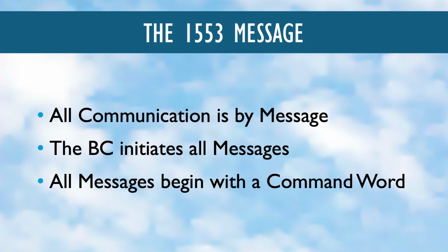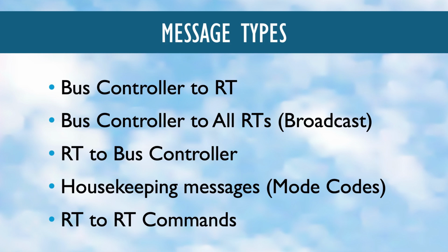We will see that there are a number of message types defined within 1553. All communication on the bus is performed using one of these message types, without exception. The first word of every message is a command word, and only the bus controller may transmit a command word. These strict rules guarantee that no two devices, which we'll call RTs for remote terminal, ever try to transmit at the same time.